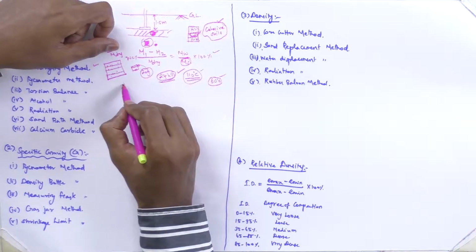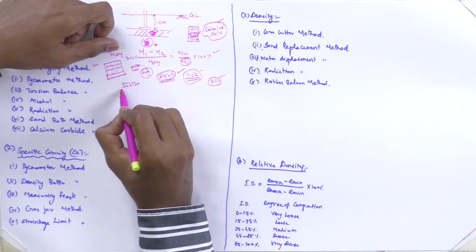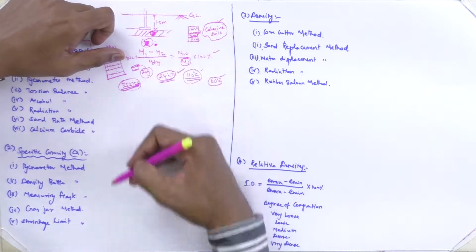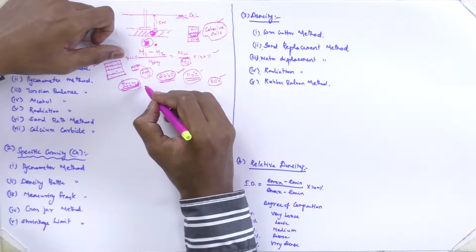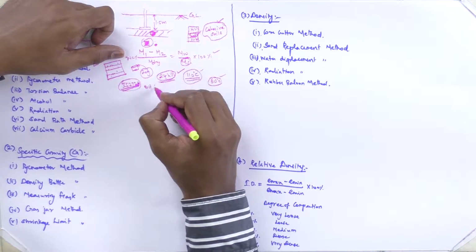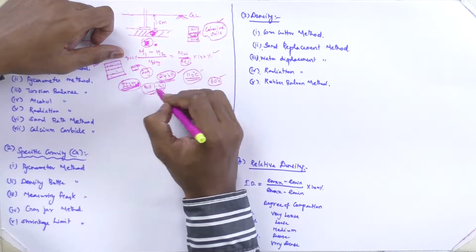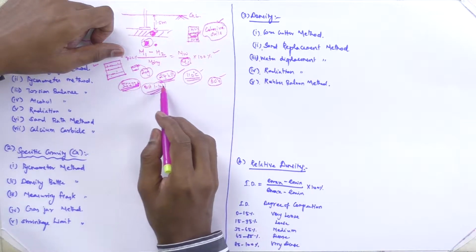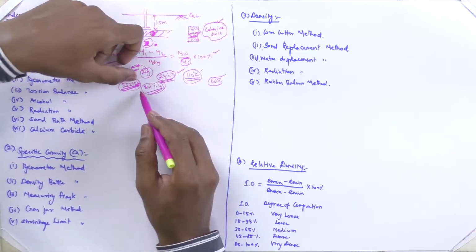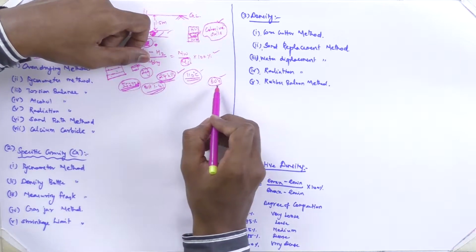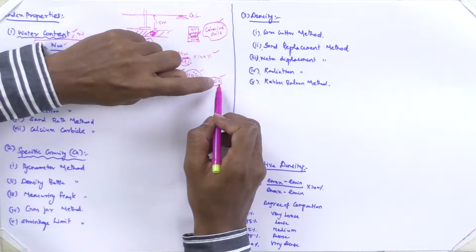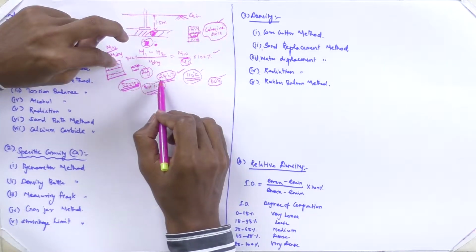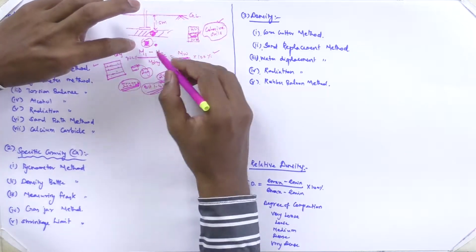This is given by IS 2720, the Indian Standards. We have parts 1 to 41 in total, with different tests, and all of these are covered in IS 2720. According to that I am talking. So 60 degrees Celsius has to be maintained for organic soil, and 110 degrees Celsius for normal soils. At the end of the 24 hours, you will get the answer, M2.